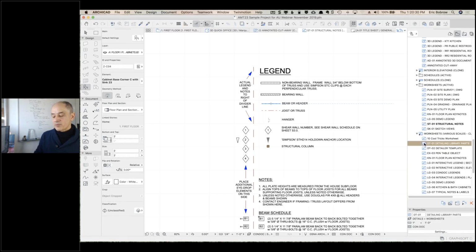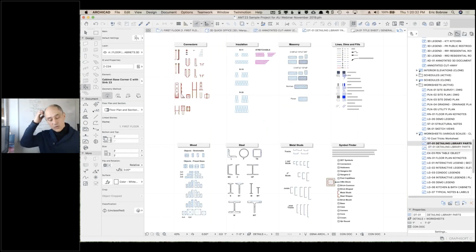So while I do recommend in general that you work with 3D models and take them as far as you can, these are 2D parts, and if we eyedrop a part here like this, this allows me to literally just place these into any detail. So you can have all of these parts that are in the standard library, but very quick way to just select them.